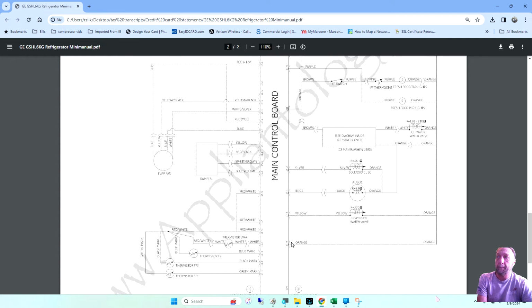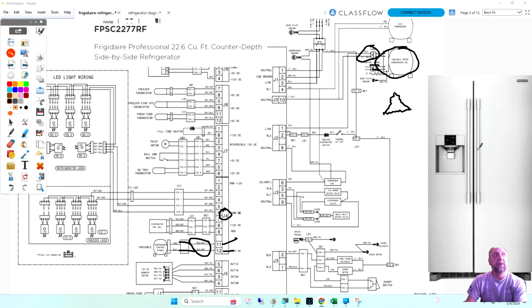Yeah, and I was thinking, well, it couldn't be on defrost because the evaporator fan was running. Yes. So it was definitely a head scratcher for me. And it might have just been an electrical connection loose, and as you're putting the cover on, you push to get it, and the connection cut the power off and cut it back on, and the time delay is just going to shut off the compressor, not the fans. Okay? But that's about the most answer I could give you without being at the unit and testing it out myself.